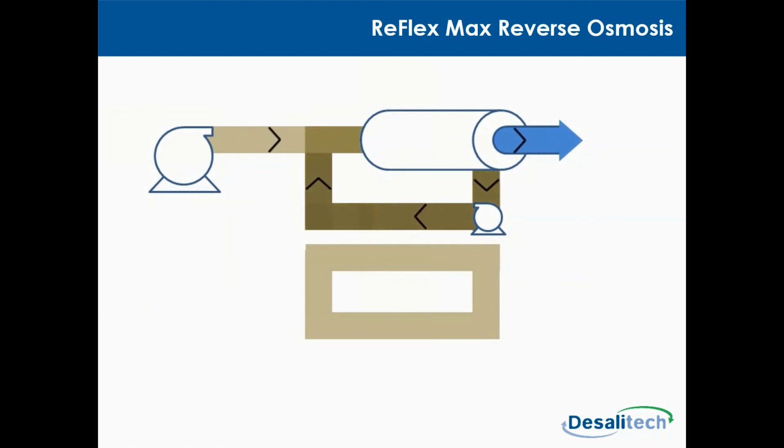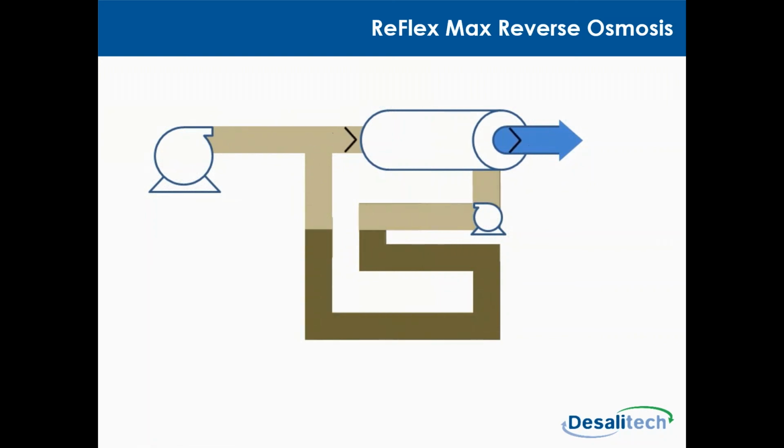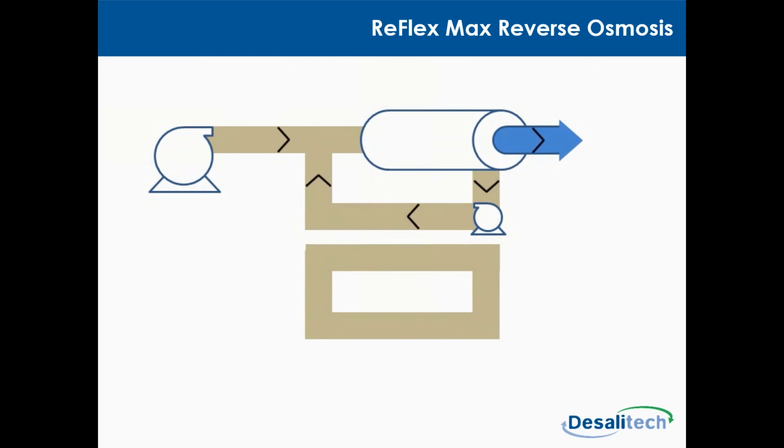You see an initial concentration in closed circuit operation. Then the side conduit is engaged, and the recirculation pump pushes the brine into the side chamber or the side conduit, and in turn, pressurized feed fills the membrane array. This goes through a couple of cycles, and again, concentration in closed loop operation, followed by displacement into the side conduit, and then the side conduit isolates again, and it's flushed out with low pressure feed water while desalination continues in the membrane loop.